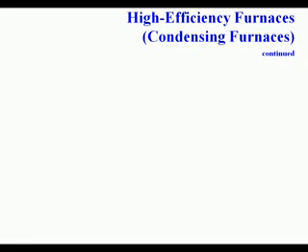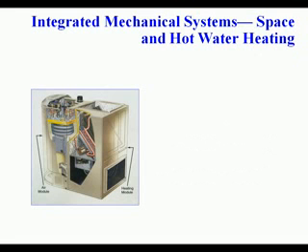These hot combustion gases are drawn by the combustion blower motor into a secondary heat exchanger. Here, latent heat is exchanged, lowering the flue stack temperatures and condensing the water vapor. The indoor blower forces circulated room air across the primary and secondary heat exchangers. Air picks up the latent heat of vaporization from the flue gases. The hot air created by the secondary heat exchanger is then circulated through the furnace duct system. The exhaust gases are very low in temperature and vented outside through a PVC pipe. The primary air for combustion is introduced from outdoors through PVC piping.